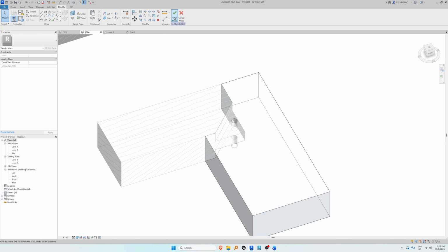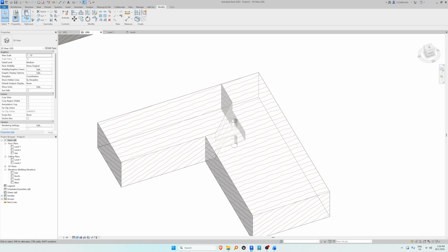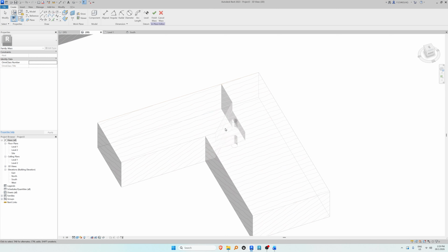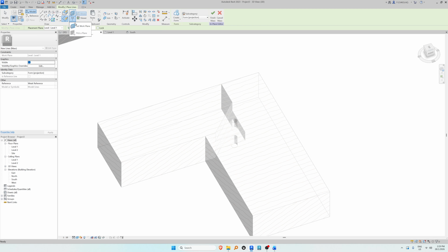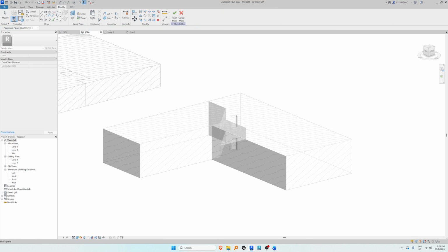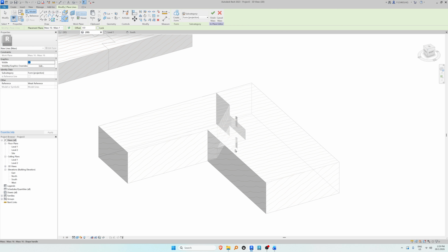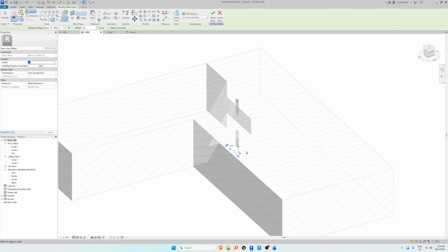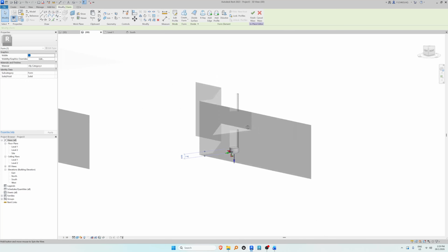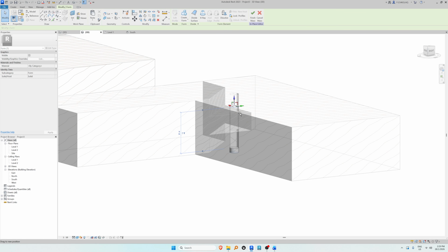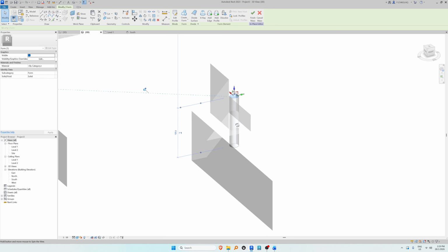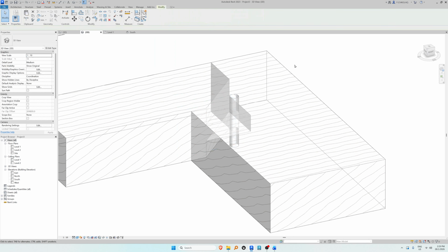Let's make the dowel next. So finish this, make the dowel. So again, massing inside, in place mass. Pick this, set the plane, pick lines first, set the plane. Let's set it to the base. Now we're gonna pick the lines. Escape, select this, create form, solid form this time. Just drag this all the way until it snaps. So now we have our dowel.